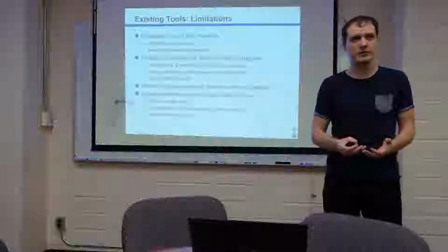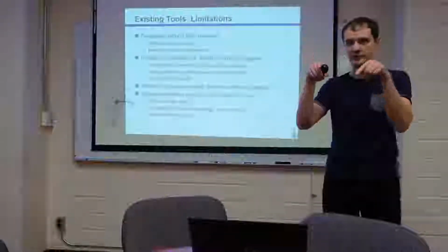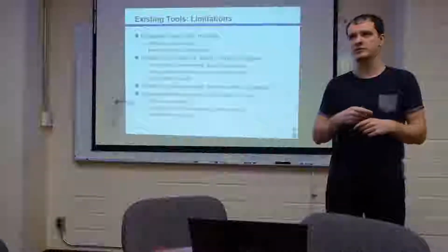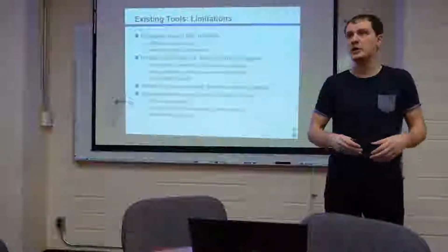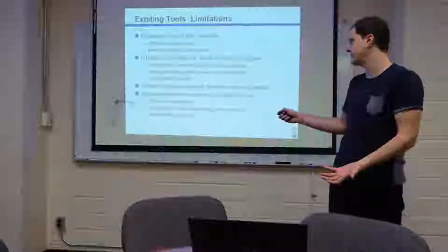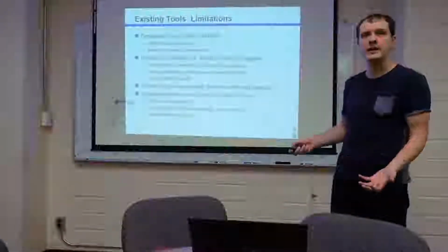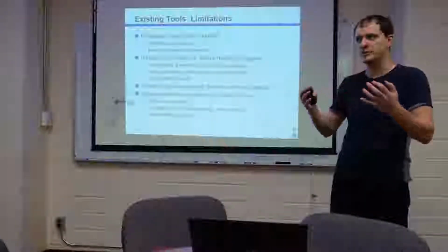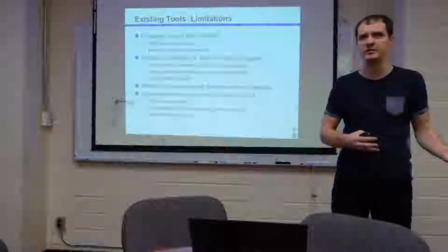And as a result, the interface protocols that I talked about, they use mostly memory mapped protocols, which is great if you're building for the use case that I talked about, but if you're not, then you have to finagle your communications to look like memory mapped reads or writes.